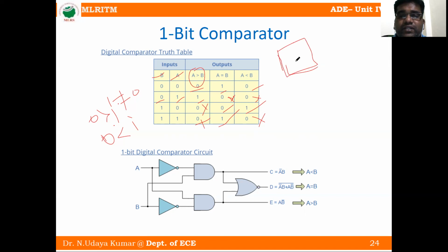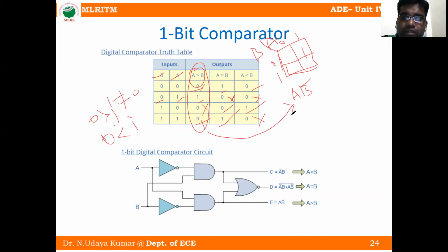A two variable K map looks like this. So this is B and this is A, 0 1, 0 1. Here this is the m0 term, this is the m1 term. The one term is 1 means here A B bar. So this one is A B bar.